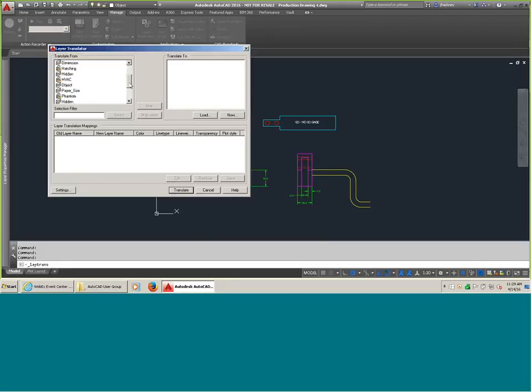This is all the layers in the drawing. Please note some of them have a little broom beside them, and you probably have already guessed you can purge those layers if you want to. One thing to be cautious of, if you hit that, it doesn't get just the one I have highlighted, it gets them all. So be very careful. You may need those layers later.